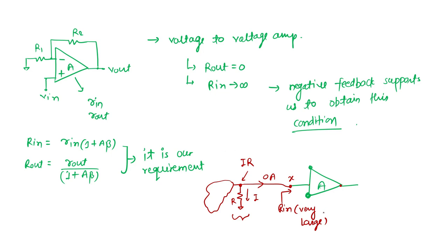And if I'm connecting my amplifier to take only this voltage, IR, at its input, and it provides some load, then the voltage at this node will not be this. I mean to say, if the current I is coming out of it, then the voltage will be I times R parallel Rn. So if Rn is some finite value, this impedance is disturbed.